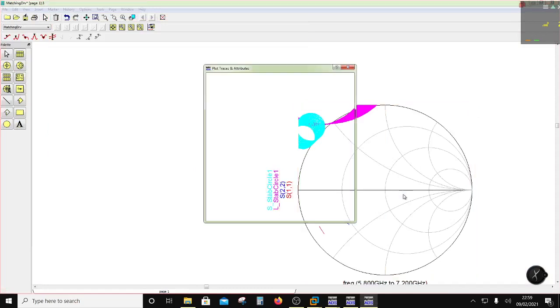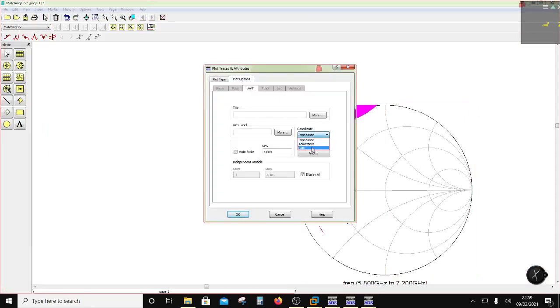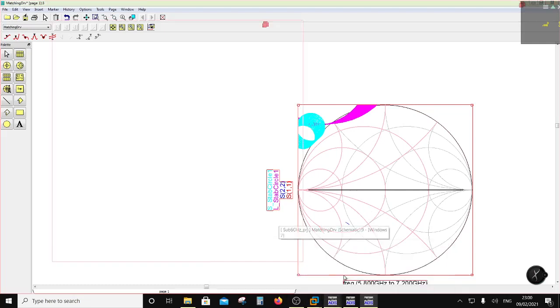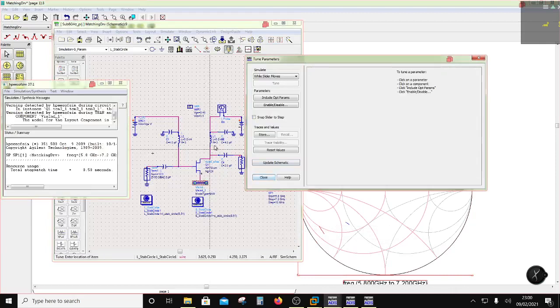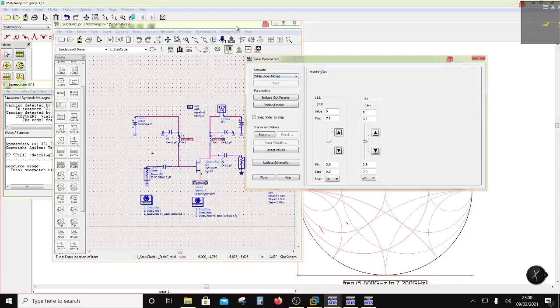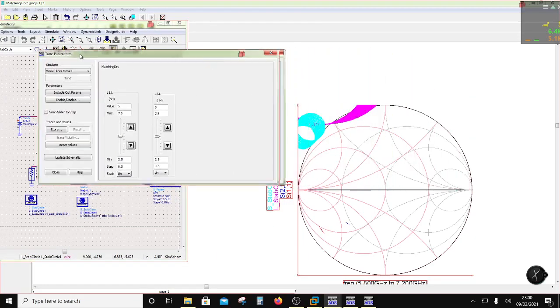So I am going to put another Smith chart on it, both. Okay, so we know I need to move this way. I will move this blue one, which is S22, this way, and the red one I'll move that way. I will use a series inductor here and a shunt capacitor, right? In this case I am going to just reduce the series inductor. Let's put a tune on this one, and a tune on this one, right? So let's see how this affects.